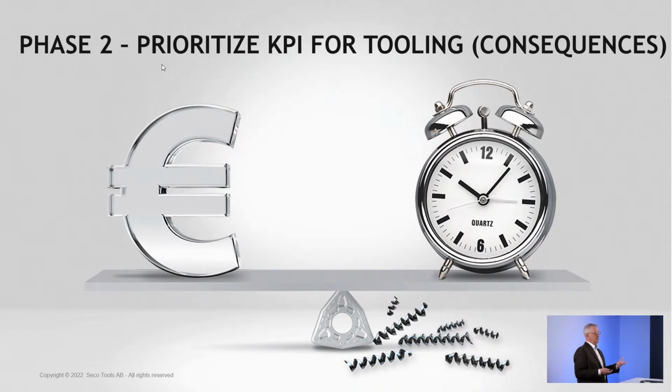And choosing means that afterwards you have something and something else you don't have. As I gave my example, square shoulder milling and face milling, if you leave it to technical specialists, they say, of course you need a face milling cutter for face milling, and of course you need a square shoulder milling cutter for square shoulder milling, of course. But if people say, no, I think more in terms of versatility, that's another approach, and then perhaps you select a square shoulder milling cutter for both applications.